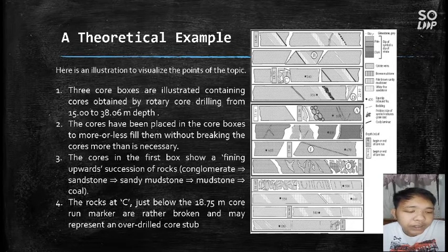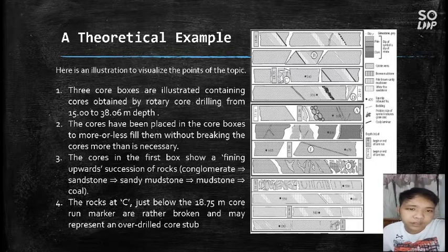One such is to be found at point A. Look at the second box, point A. They would not be counted as natural discontinuities for RQD measurements. So, in logging, the first step is always observing the breaks in the core.